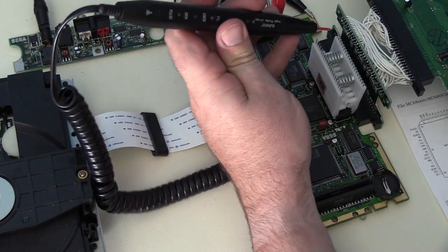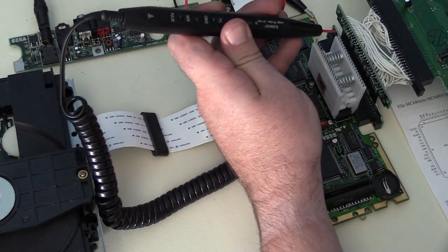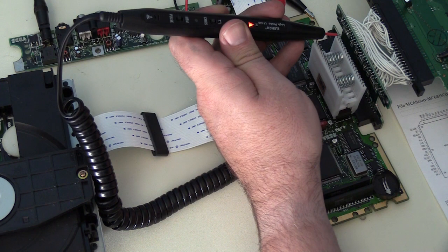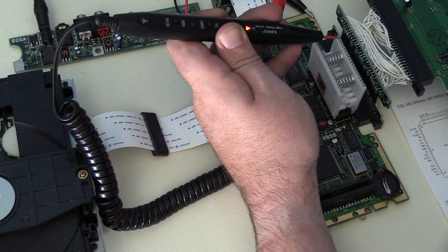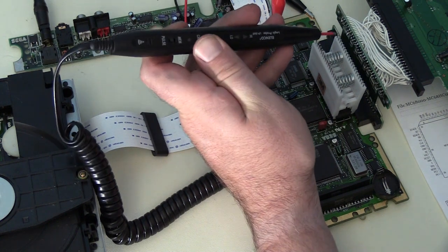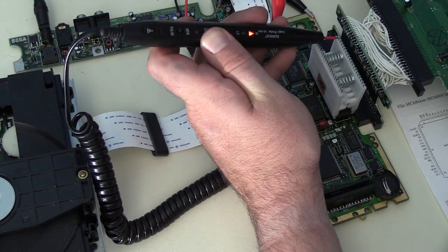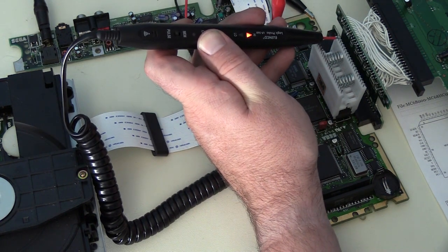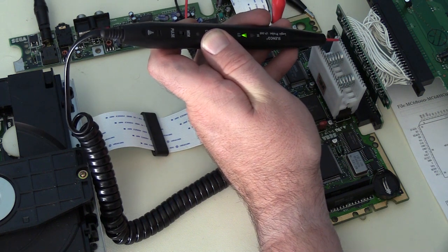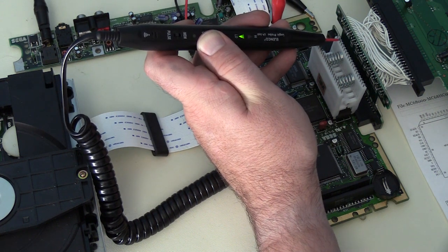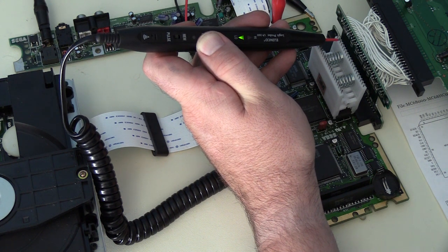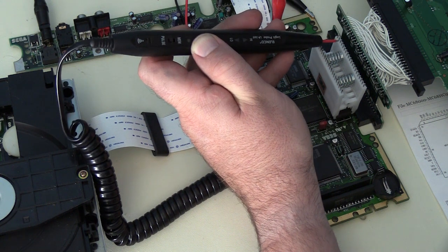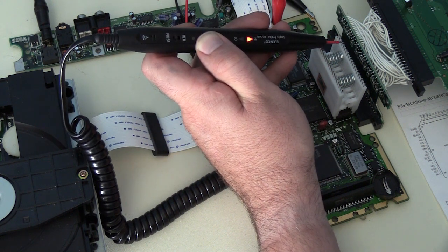And then for the other side, we've got another voltage pin there, that's high. Programming line, that holds high all the time unless you're programming it with a chip programmer. Then this one shows is not connected in the schematic, but I guess the Sega CD gives it a low signal. Doesn't really much matter in this case. And then next pins are our address lines.